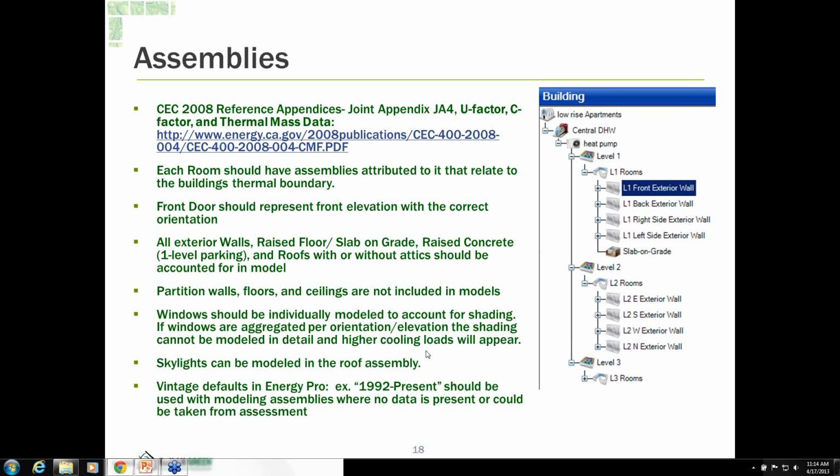Let's see. I always have exhaust fan, non-res only. I'm not too clear on that question. I haven't run the exhaust fan calculations in the non-residential module to see what the loads come out to, but it would be my assumption that it does include that in the calculations. But there is a residential tab in Energy Pro for mechanical ventilation.